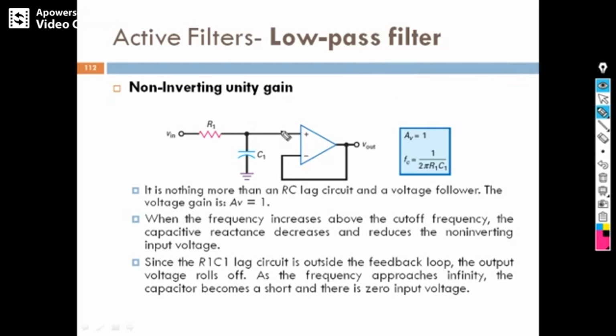The diagram you can see here. See, in the operational amplifier, we have connected the output directly to the input, as a feedback to the input without any feedback resistor. That means it is a unity gain. It will not amplify actually. It is called unity gain. It will not amplify. Understood or not?